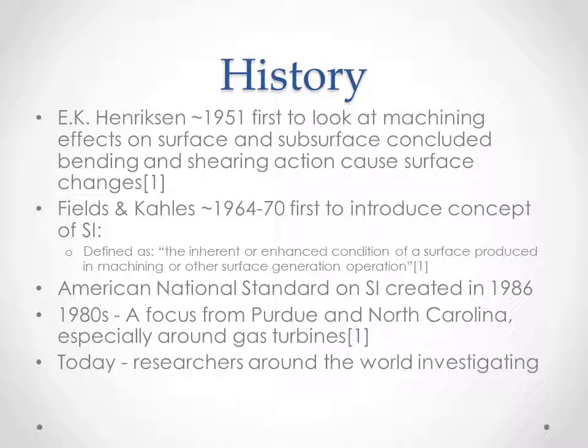A little bit of historical perspective. A gentleman in the 50s, Eric K. Henriksen was his name. He was the first one to, I'm sure there were others too, but he was the first one to approach it from an engineering/scientific standpoint, and look at how the machining affected the material property or the surface property, and if that could be changed or modified, and what effect that had on the long-term life of the component. He realized that the shearing effect causes the bending, and that of course causes hardening and other different things. So obviously, just using basic engineering principles, that could be modified.